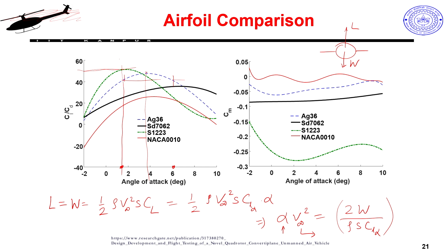So, I can maximize it here when I want to go straight towards the target. I may operate here, which will be probably 50 or so, or 45 or 48. Once I go back to loiter, I will operate probably at this high angle of attack, which will ensure lower speed, but I still have reasonably high L by D. But when I want to minimize my power, there is a different requirement, and we will look at that in coming lectures.